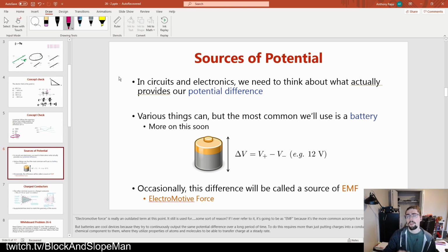So what do you do? You don't run away. Probably shouldn't hop either. The best approach is to very, very, very slightly shuffle your feet back and forth going forward, making sure that there's not much distance and going directly away from that downed power line. Or maybe at an oblique or something like that. But the point is, you're trying to move away and you're trying to shuffle your feet the entire time.